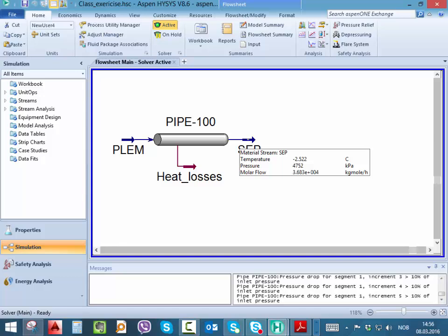That happens only when you have gas, or a fluid that is mainly gas. It's because when the pressure goes down, you also have a cooling effect. I'm not sure if you have had that experience in processing, but when you pass a gas through a valve with a pressure drop, the temperature also goes down. It's exactly the same principle. When the pressure goes down along the pipe, the temperature will also drop. It's called the Joule-Thomson effect. I'm going to put it written later.